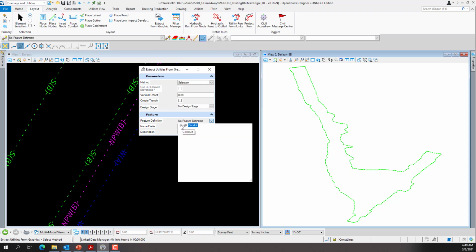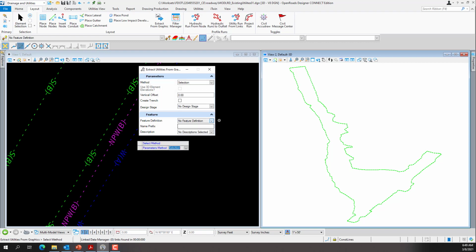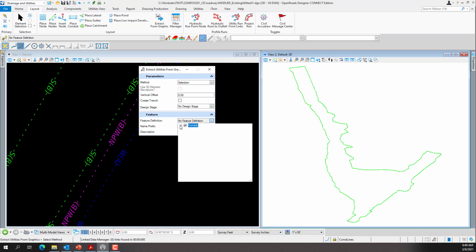You'll notice that it's going to be a conduit folder, and then within the conduit folder we'll see the different categories. We have communications, electrical, gas, stormwater, wastewater, water segment, and generic segments. So this is in the water segments for existing. We have two categories under that, non-potable, so we'll use that for this line, or a water line. And if you go off the tool to show you like I did, you'll have to come back. So we'll go back to the water segment, existing. We'll pick on a water main.